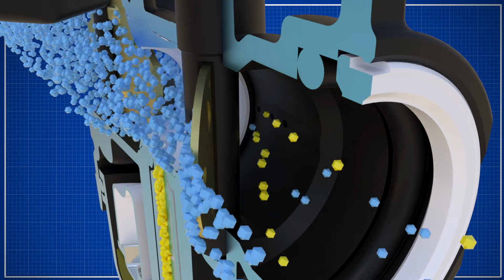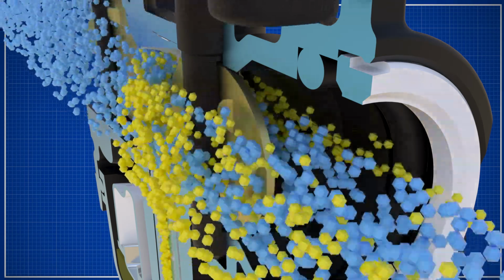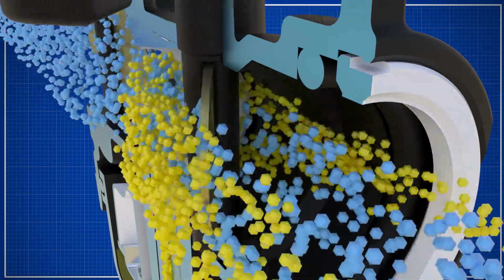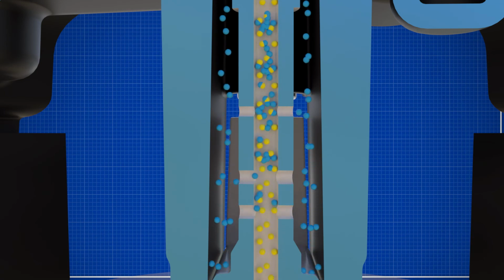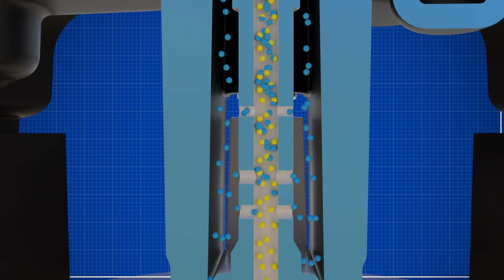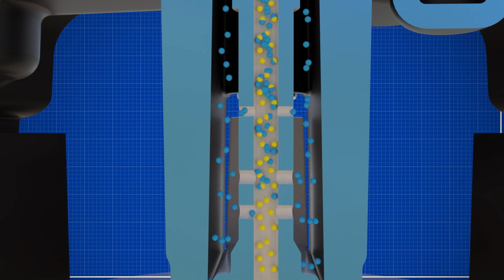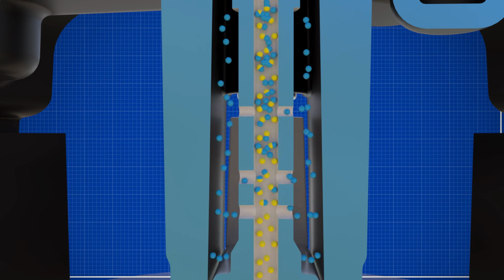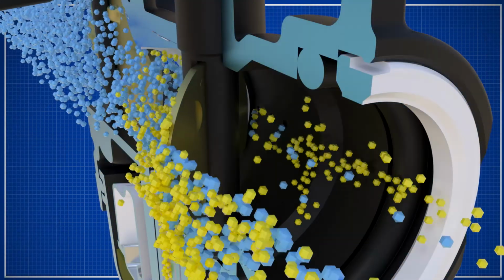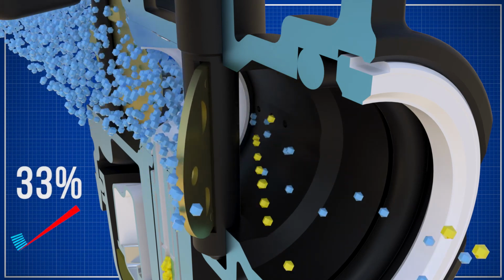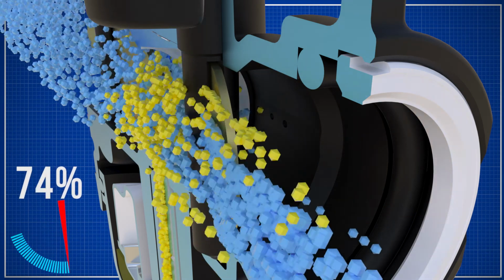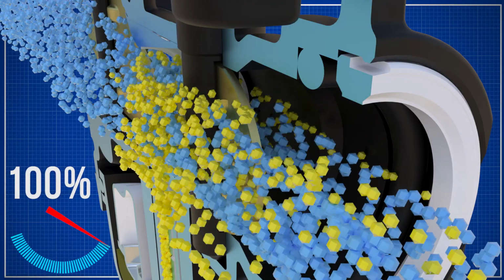When the throttle plate opens, the airflow in the carburetor will increase. The venturi will make the necessary pressure change to move the fuel. In the bowl area, the fuel is metered only one time through the main jet. The fuel is pushed up the main nozzle and starts to atomize immediately. The high-speed air bleed circuit supplies the holes in the outside of the main nozzle with air for this mixture process. The high-speed circuit will start to supply fuel when the throttle plates start to open from 25% and remain active to 100% throttle open.